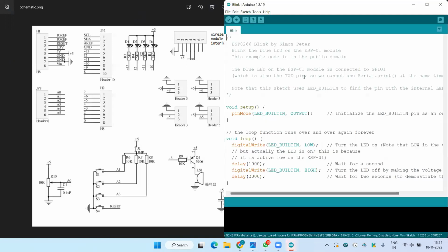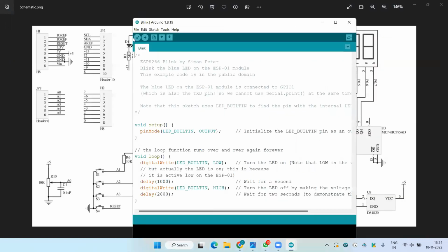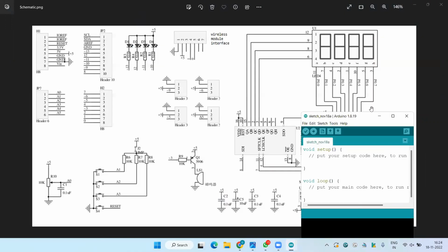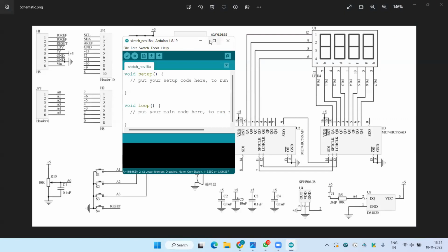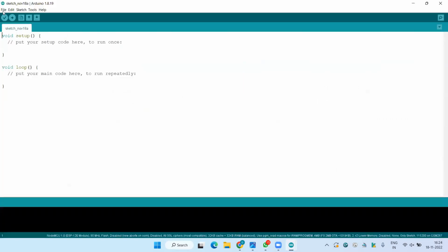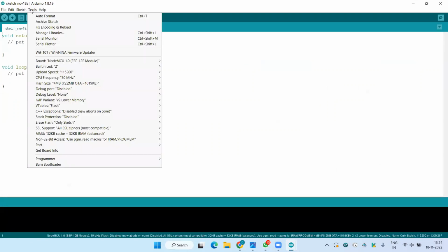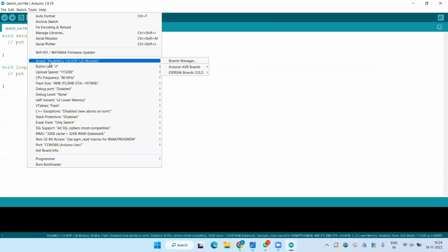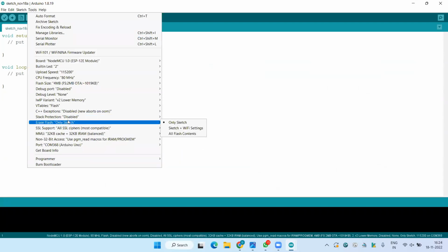So this is our program. This is the Arduino IDE. The IDE is generally used for writing Arduino programs. First of all, we need to create an environment here. We need to check whether we have connected the Arduino properly or not. For that, we need to select the board. Here you can see the port to which the Arduino is connected, COM368 is the connected Arduino board, and we need to select which board we are going to use. Our board is Arduino Uno.